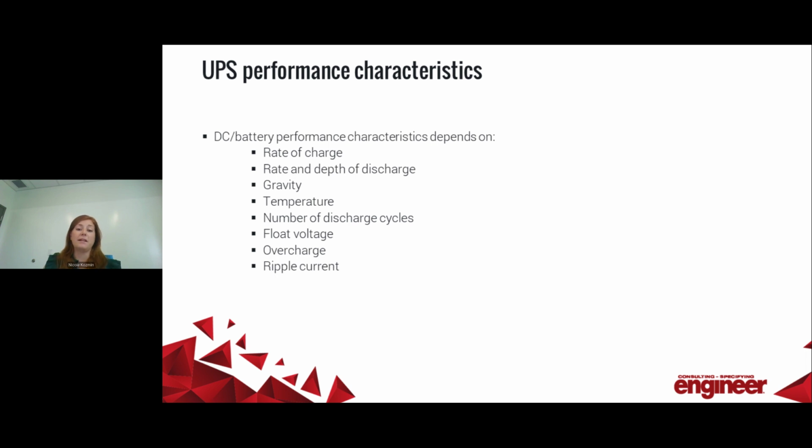If they are over 20 kilowatt hours, they cannot be located in rooms where the floor is more than 75 feet above the fire department vehicle access or more than 30 feet below the finished floor of the lowest level of exit discharge. Each battery array, limited to 50 kilowatt hours each, needs to be spaced a minimum of 3 feet from other arrays and from walls in the storage room or area, unless closer spacing is allowed by the authority having jurisdiction based on performance in UL 9540A testing.